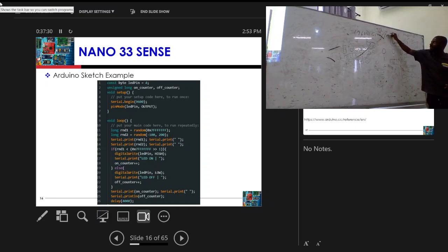The same thing with multiplication. Another very complex operator in hardware, very difficult to do. If I want to do that and the number is 2 to the power of something, what will I do? Division was right shift by 1 or 2 or 3, and I will be able to divide by 2, 4, 8. If I want to multiply a number by 2, what will I do?